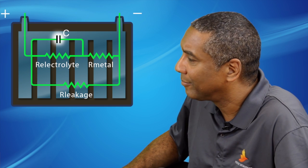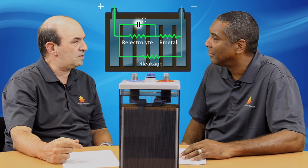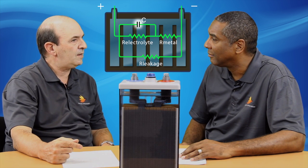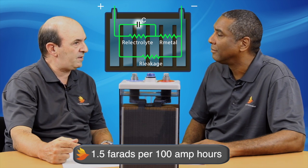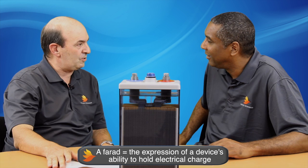The capacitor C is very interesting. It represents the inertia in the electrochemical voltage generator, which causes it to react slowly to rapid changes in load current. C is a measurable parameter and typically runs about 1.5 farads per 100 amp hours of cell capacity. What did you say a farad was again? A farad is the expression of a device's ability to hold electrical charge.